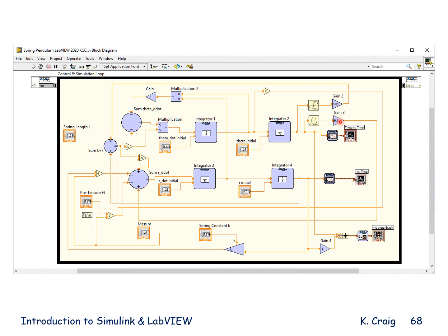It's permissible to put 9.81 into the diagram as it will not change. We don't want to put values in our simulation diagram, as in Simulink, that will change. And if we do, then we input them through numerical control on the front panel. So this is G cosine theta, and theta is in radians. G cosine theta, which I follow around, and it goes in with a plus sign. That then is my second equation.